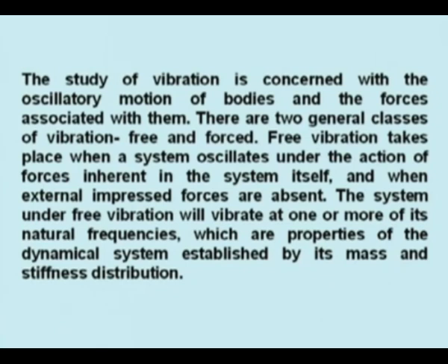Now, if we take a spring mass system and disturb it, that means we displace the mass by some amount, then this motion of the mass starts, and this is called free vibration. The spring force is always present, and at the same time you have inertia force. The body is under equilibrium under the spring force and inertia force.